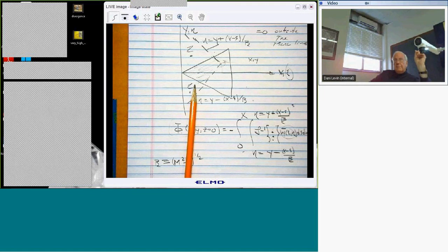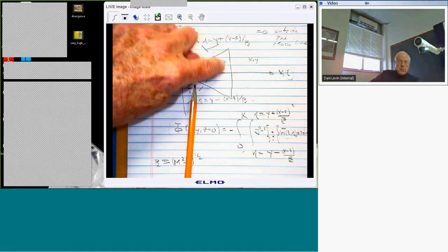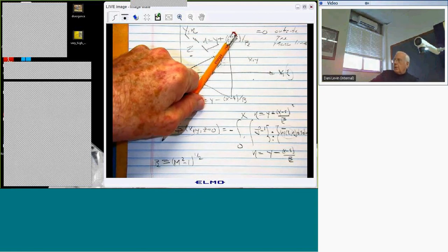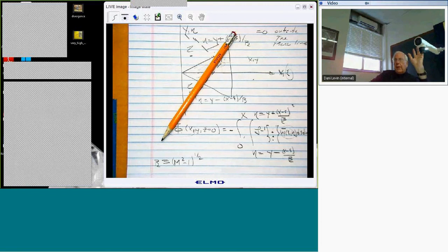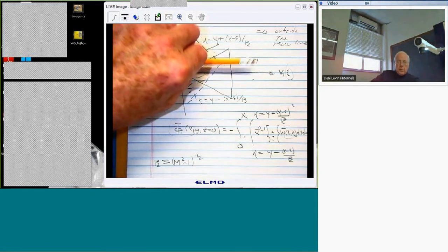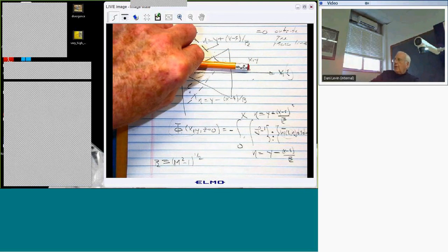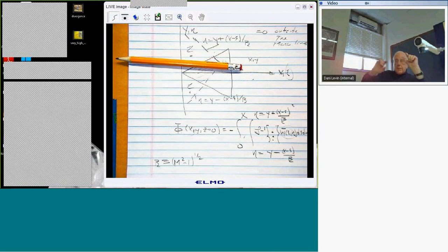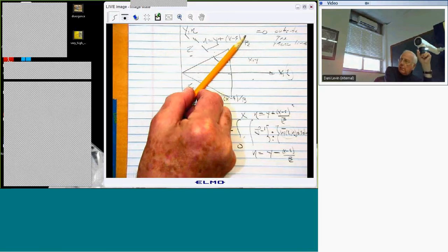Okay. And normally, for numerical reasons, you make sure that the boxes are such that the diagonal of the box is along the Mach line. It turns out that gives you a better numerical behavior than other possible choices. You don't have to do that, but that gives you better numerical behavior. So the methods that people have employed historically for supersonic flow are called Mach box methods, because the boxes are always aligned such that the diagonal is parallel to one or the other of the Mach lines.